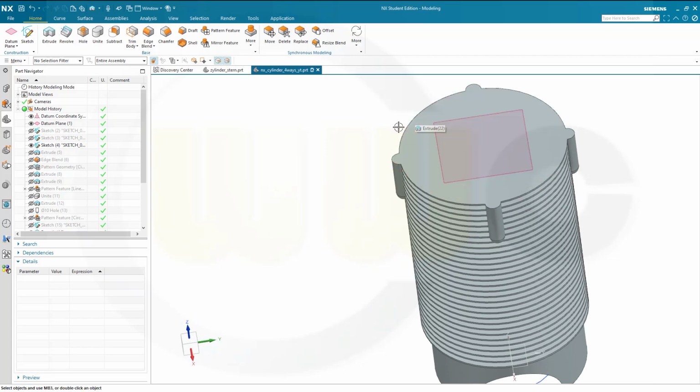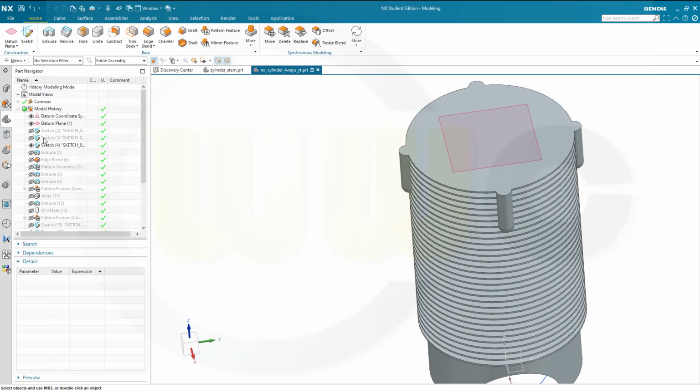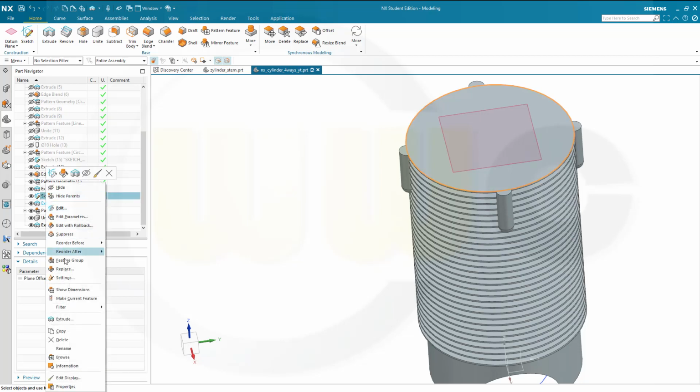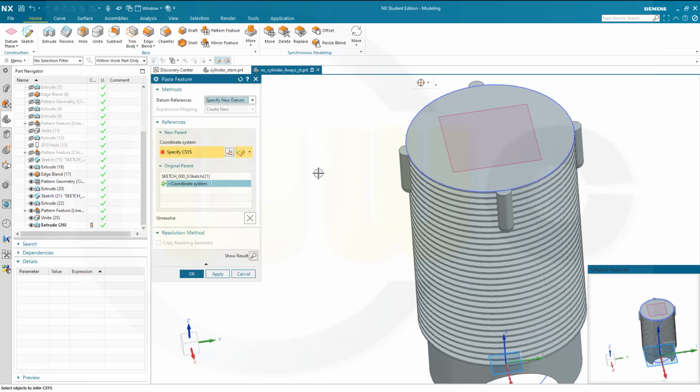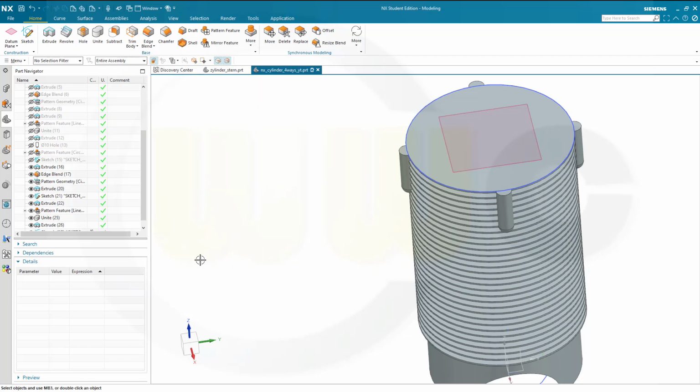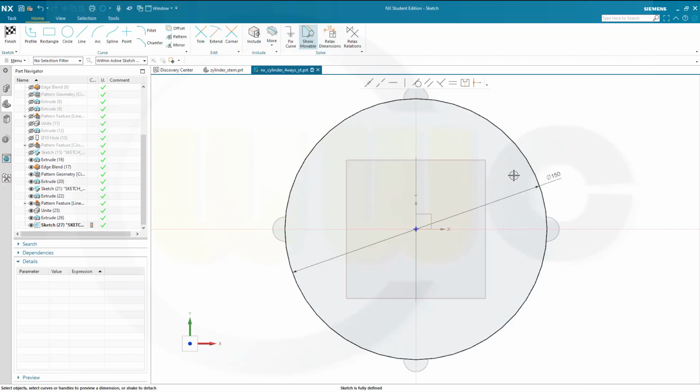And I could do this with a hole or with a sketch. If I want to use a sketch, that would be that sketch here. Nope. I think that's the one. That's the one. I could make a copy of this one. So copy it and paste it. Control V. If you change nothing, it will go to the same plane. So there's a new sketch, this one, and I want to give it a smaller diameter, and that would be 126. Confirm.